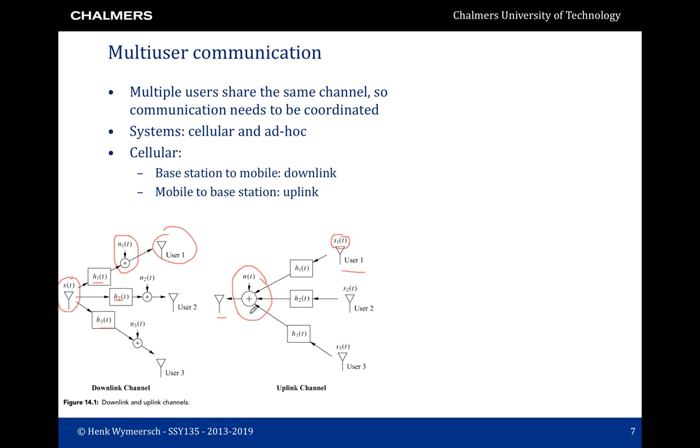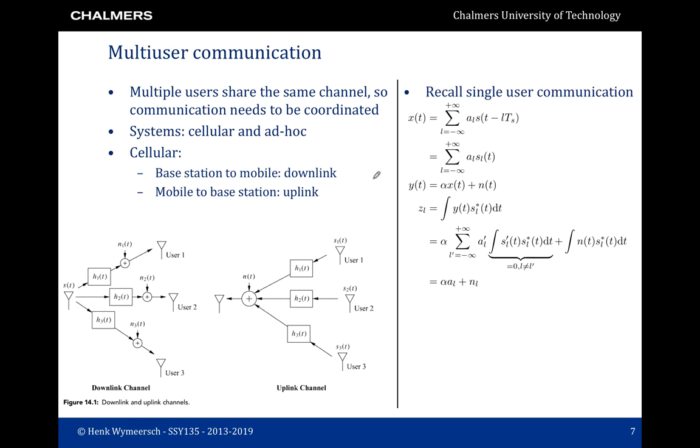We recall that for single-user communication we had the following scenario. We have a transmitted complex baseband waveform, which comprises an infinitely long sequence of pulses s(t), each spaced a symbol slot duration Ts apart. Ts is approximately 1 over the bandwidth.